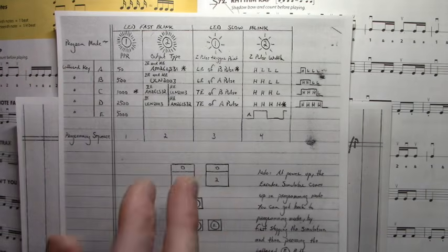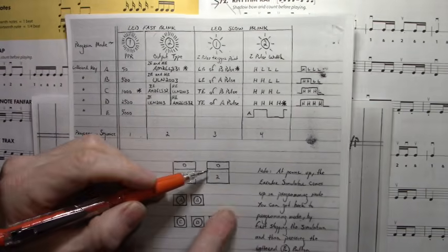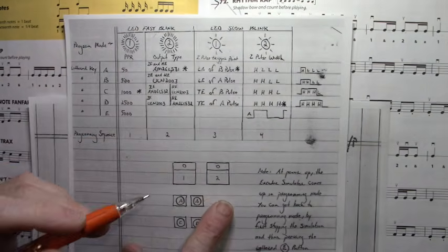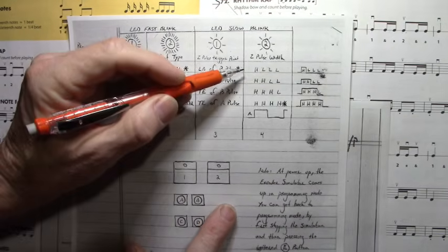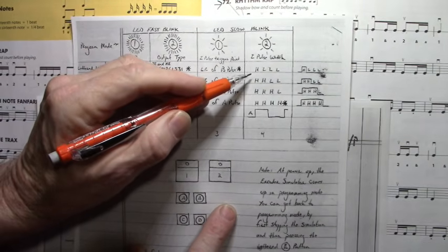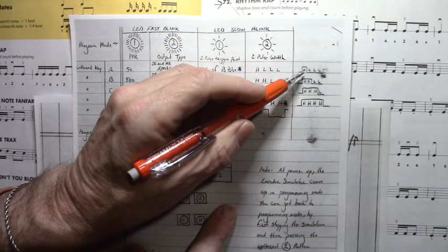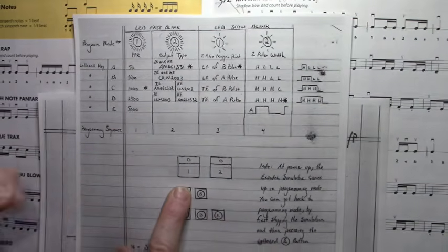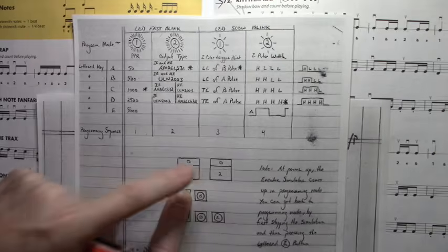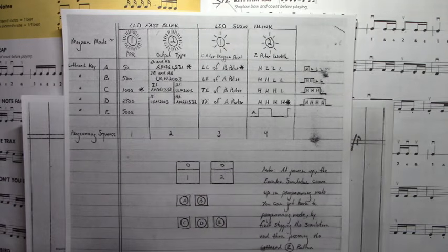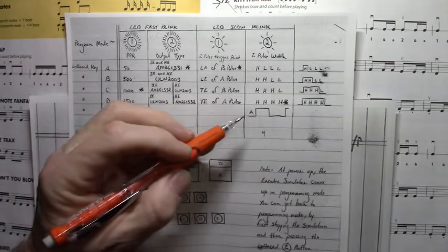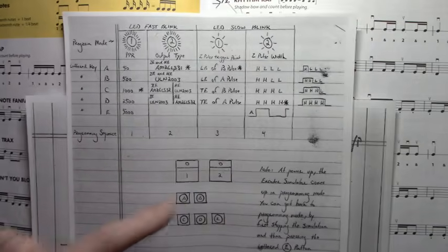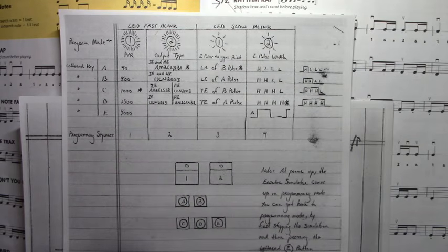So the width of the Z pulse, now we're on switch number 2 right here, and the LED is blinking slowly. And let's say we wanted just a very brief Z pulse, and it would look like this: high, low, low, low. We would push the A button and then push the number 2 switch, and we're fully programmed. But if you want the default, which is mostly high, you would just push the number 2 button right here. Now that's how you set it up.